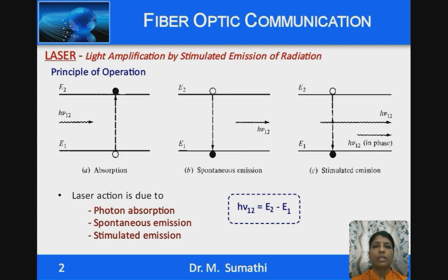In the previous video on LED, we had compared a laser with an LED. A laser provides high intensity, coherent, narrow beamwidth light which occupies low spectral width, and it is widely used for optical communication applications. The disadvantage of laser is its high cost, high temperature dependence and short lifetime. Now we shall discuss the principle of operation of a laser.